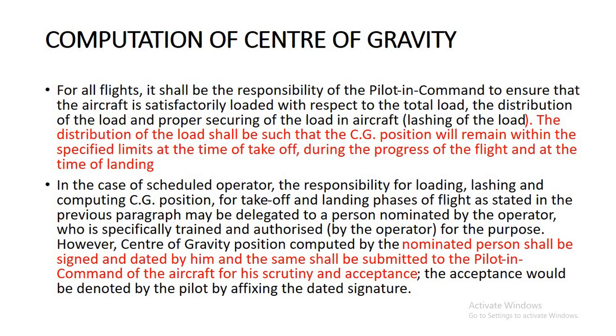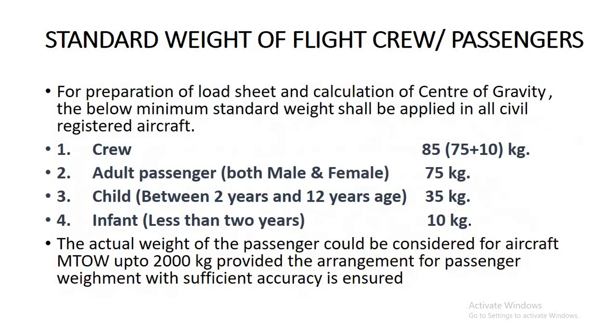However, the load sheet created by the nominated person shall be signed and dated by him. The same shall be submitted to the pilot in command of the aircraft for scrutiny and acceptance. Acceptance is denoted by the pilot by affixing his dated signature. So ultimately the pilot in command is responsible. He can delegate it to some person in the airline, and the pilot can accept by placing his signature. That's all.